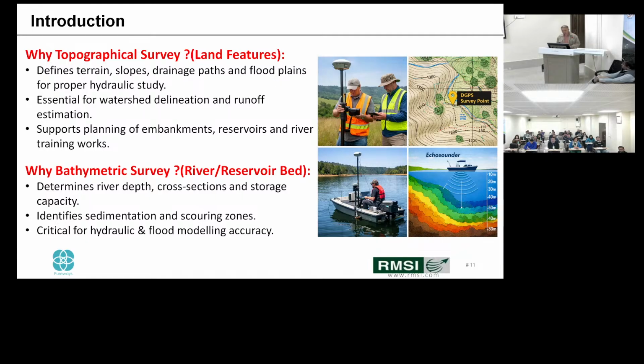There are new technologies coming up. Before, we used to do surveys using a total station, taking the cross sections and all. Now there are developed, fast and reliable instruments like the DGPS and echo sounders, and aerial technology like RTK, photogrammetry, and LiDAR technology, which we are currently using right now. This will help us in defining a good terrain for the hydraulic study.